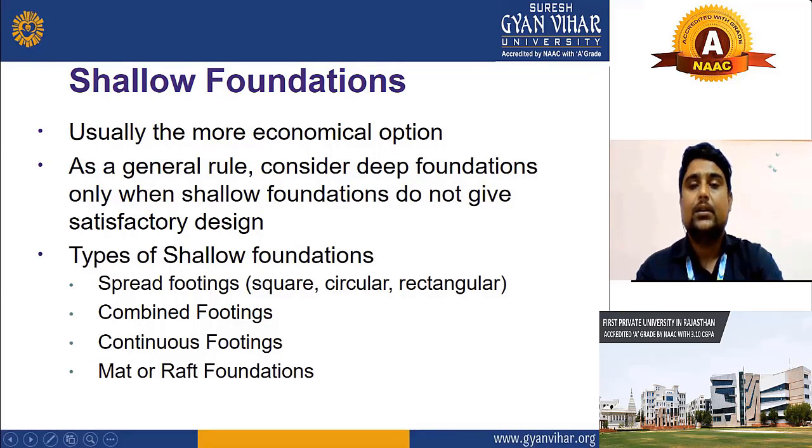You cannot make a deep foundation for a lightweight structure, because you can make it, but what will happen? The cost of your structure will increase, and in this case your structure will not be economical. That's why we only prepare a shallow foundation for a lightweight structure.